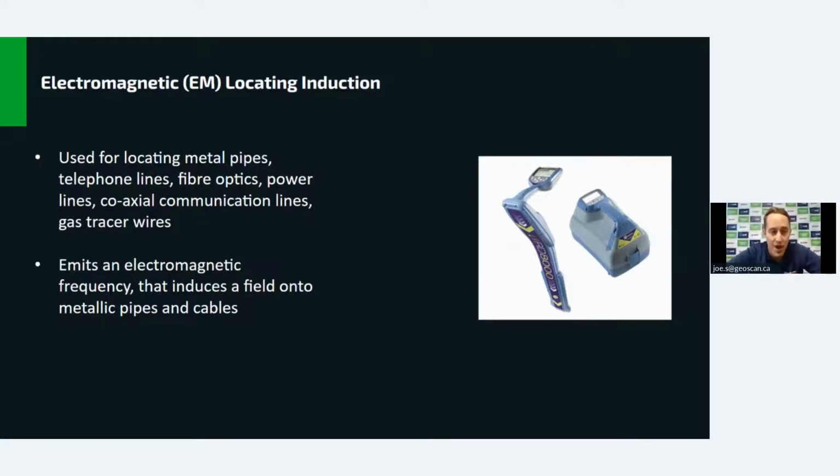The transmitter is grounded, and so the receiver effectively picks up the completed circuit. And that receiver, in the hands of an experienced and knowledgeable and skilled operator, will be able to effectively trace out where that line leads to.